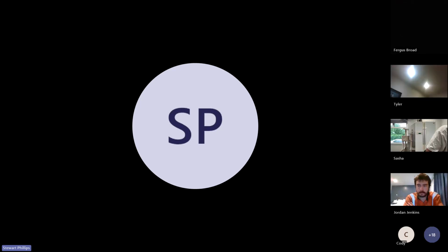Yeah, the main ones we talked about last week were your MCB, or miniature circuit breaker, which protects against overcurrent and short circuits by tripping the circuit. You've got your RCCB, or residual current circuit breaker. We commonly just call them RCDs, but RCD is a broad term for multiple types of different RCDs. They detect leakage currents to prevent electric shocks. And then your HRC, or high rupturing capacity fuses, provide high breaking capacity for industrial and high current applications.